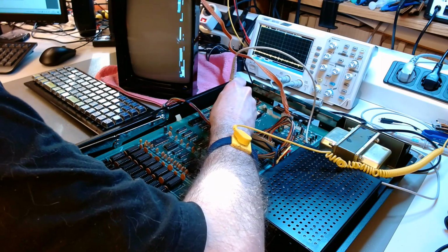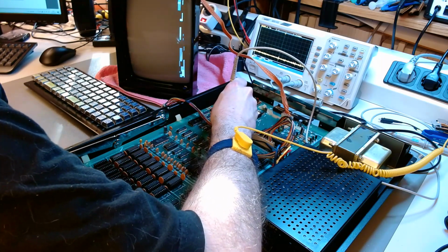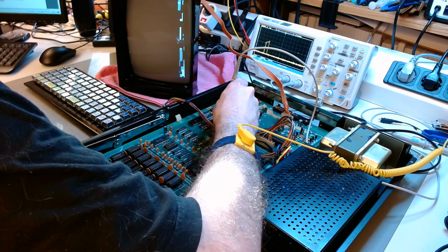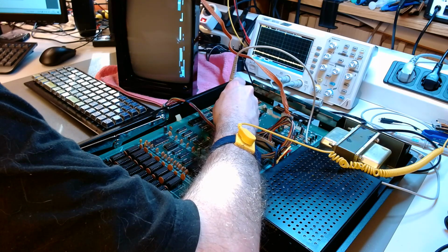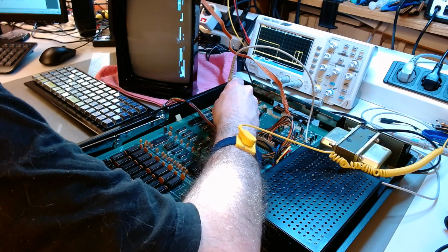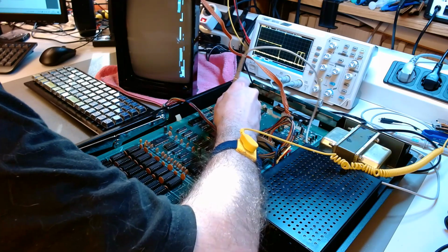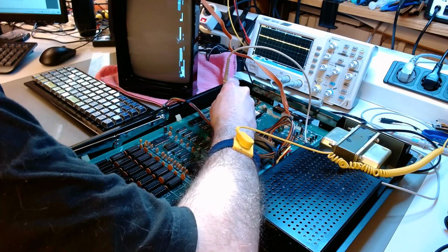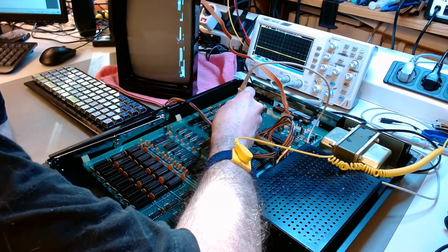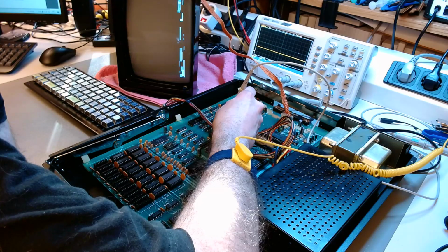That's the serial and other bits of the parallel load. Yeah, the computer is loading character bytes into this shift register, but it's not shifting. Let's look at the power level. Power level is okay. It's not shifting because the clock input is floating.